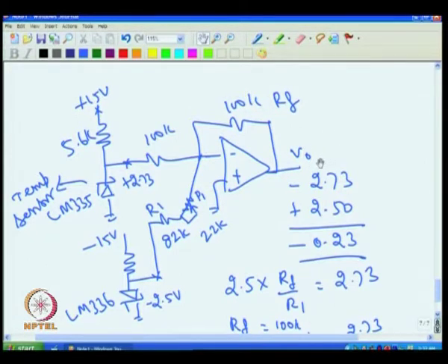So, what I do is, if this is going less or more, then I should be able to adjust. Some of the sensors may go even more than 3.73, may go to 3.74 at 100 degree C. So, I should be able to adjust when the voltage is less or more. That I can do by varying the gain here, because if it is not 3.73, only 3.72, all that I need to do is go more than 100k, because if both are 100k, gain is 1.